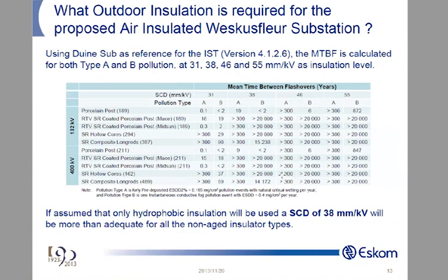So what I would do, for instance, is have a little in-service test station online. I build it, it's easy. You can use the existing tower, put up nine insulators on it coated with different coatings from different suppliers, and you evaluate them, and then you must live with the fact that one or two of them are not going to make it.